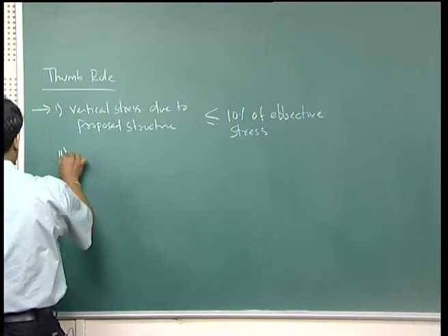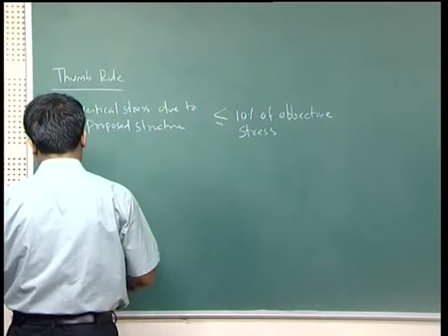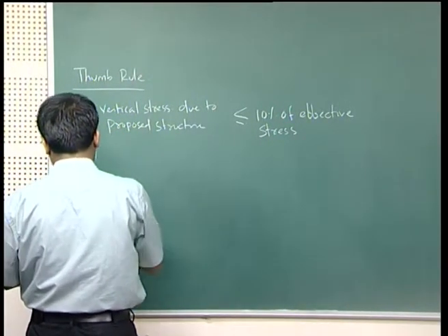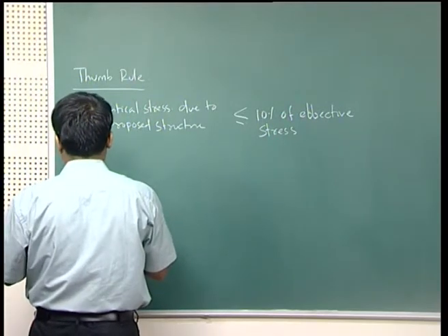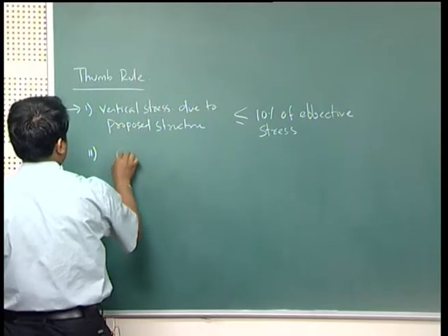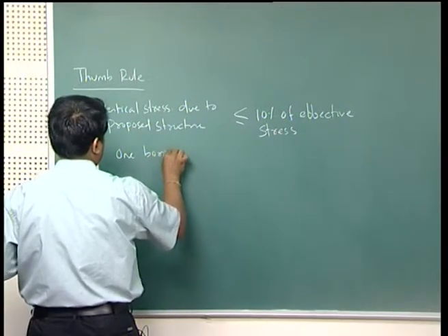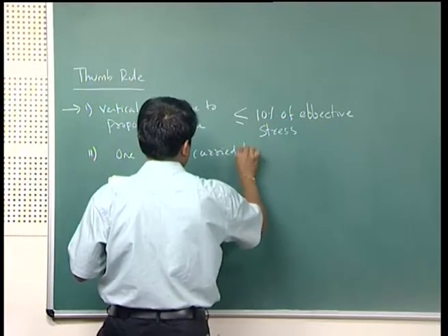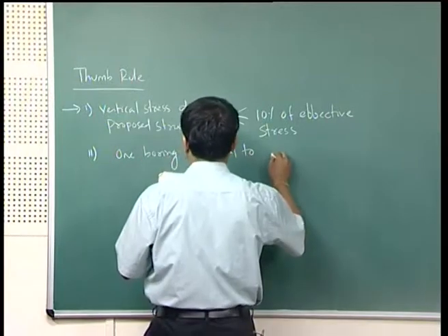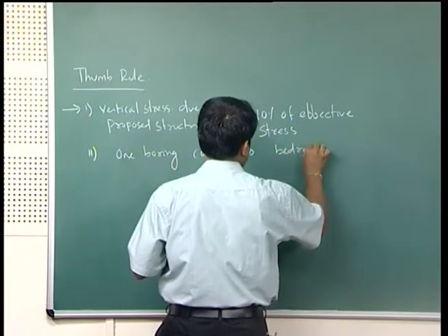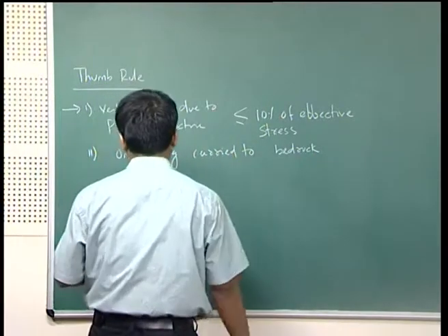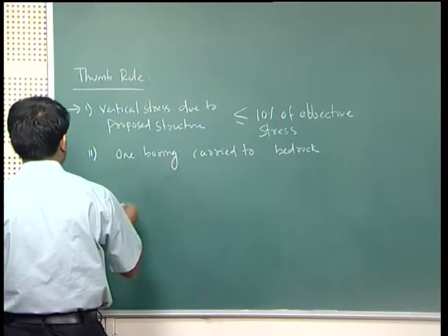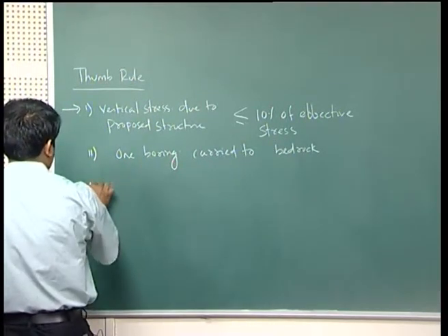Then it may be so one boring carried to bedrock, or at least to a level below the anticipated level of influence of the building, where maybe bedrock comes into the picture.